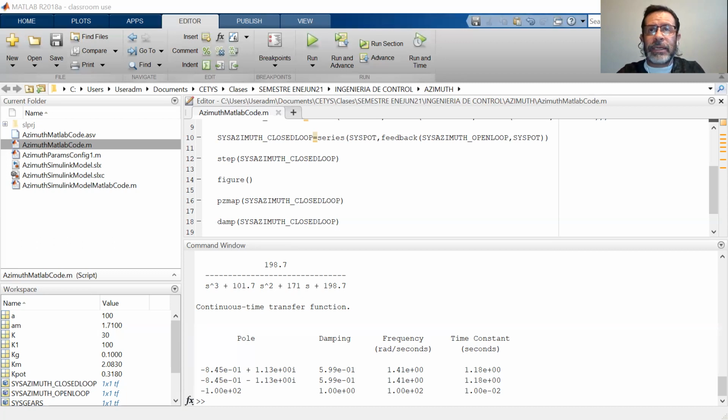It kind of follows the exclusion principle. The closer you get to one parameter, the further you get from the other. So the lower the overshoot, the slower the system. The higher the overshoot, the quicker the response, or the quicker you get to the target value. So you're always playing with those trade-offs, and it depends on the type of response you want for that particular system.